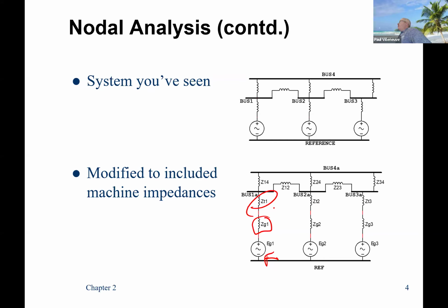So I would like to do nodal analysis on this, but I can't, can I? Because the premise of nodal analysis is everything is in parallel, right? These are all in series, aren't they? So the very first thing you do, and this is the most important thing you do, you have to combine all your series resistances or series impedances first. You can't do anything with Y-bus until step one, combine any series impedances, okay?